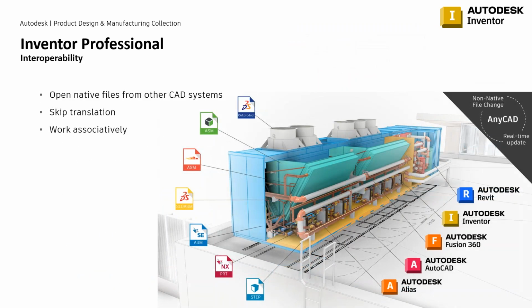Inventor also has an extreme amount of interoperability or associativity to other file types. Starting a couple years ago, Inventor added this technology called AnyCAD. This allows you to bring in models from all these different sources, and they can either be converted, which is very traditional, right? We take, let's say, a CATIA file or an NX file, and we convert it into an Inventor file. That's something that's always been around.